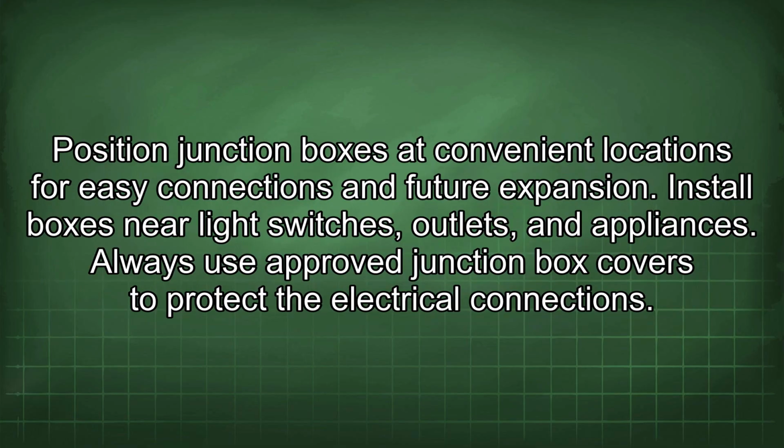Position junction boxes at convenient locations for easy connections and future expansion. Install boxes near light switches, outlets, and appliances. Always use approved junction box covers to protect the electrical connections.